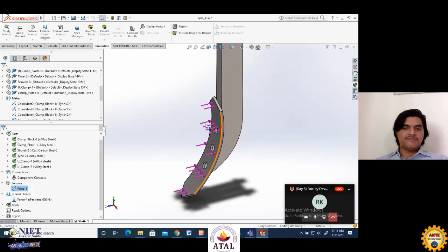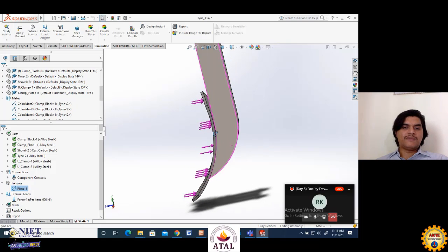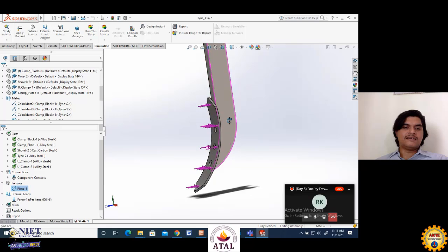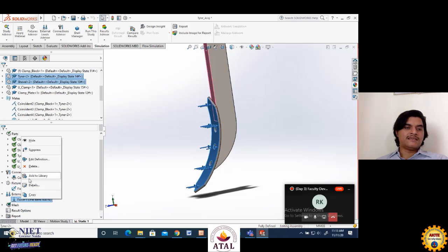When the Tine is moving forward, the load is acting opposite to the direction of motion, parallel to the ground. See, the same load application I have indicated onto the Tine over here under the fixed load condition. Here I have taken 60 kg force or 600 Newton. I have given the value as the force.